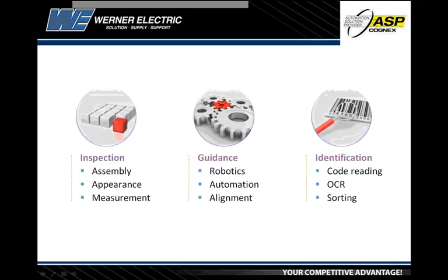There's a very wide web of material moving through the machine at high speed, and those webs have to be steered. Web steering requires some feedback about where the edge of the web is on the machine, and you can use a vision sensor, a low-cost camera in the $1,500 range, to do that.